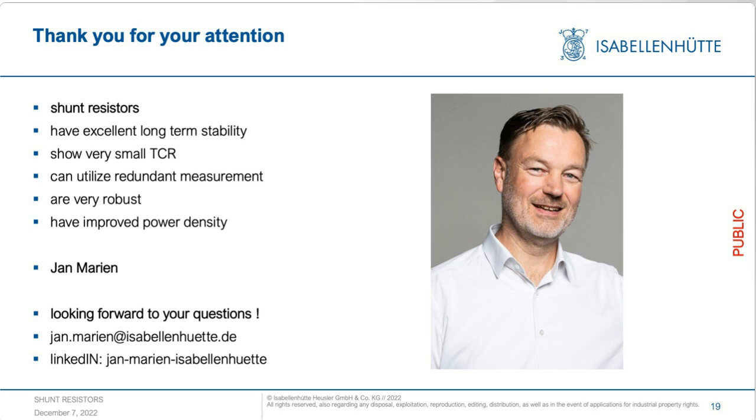If you use a material with a higher specific resistance, then you have less material applied, or if you use a lower resistive material, you need to use more material to get the same resistance value of the shunt.